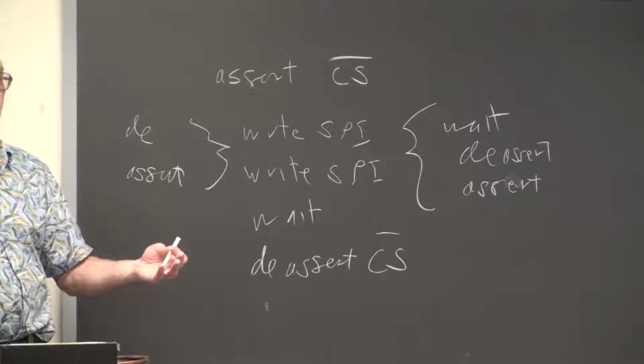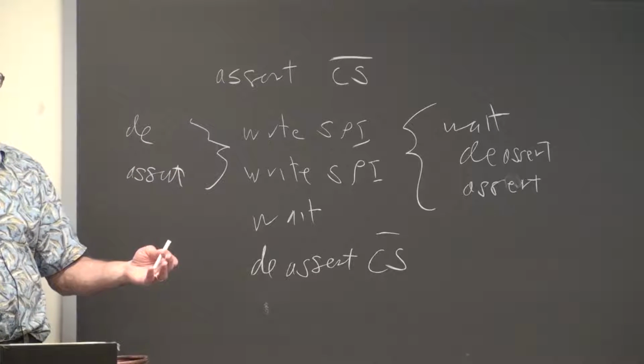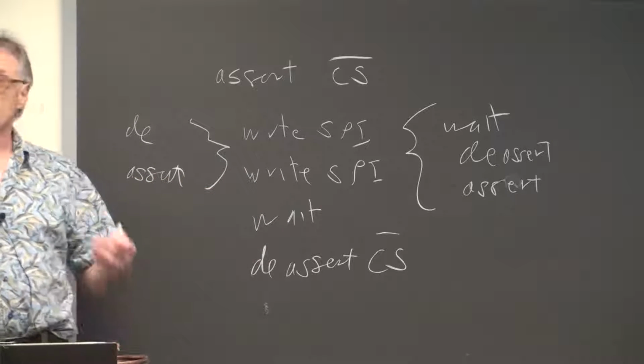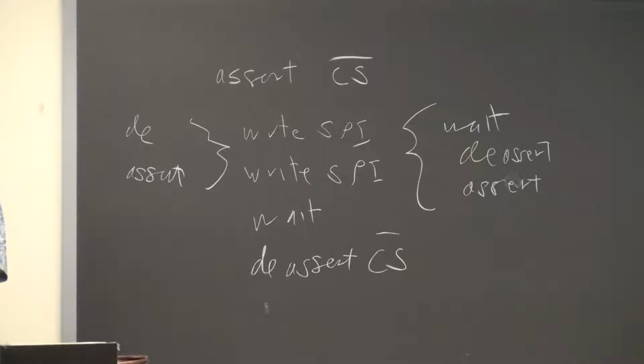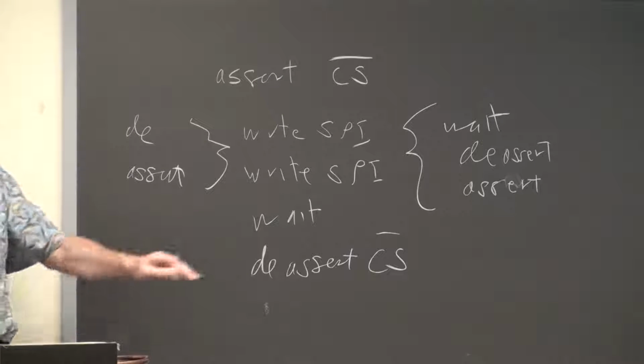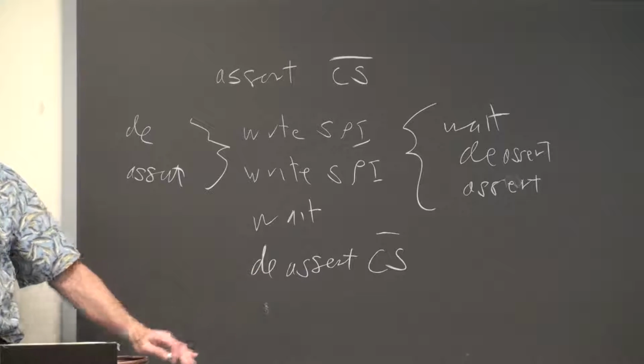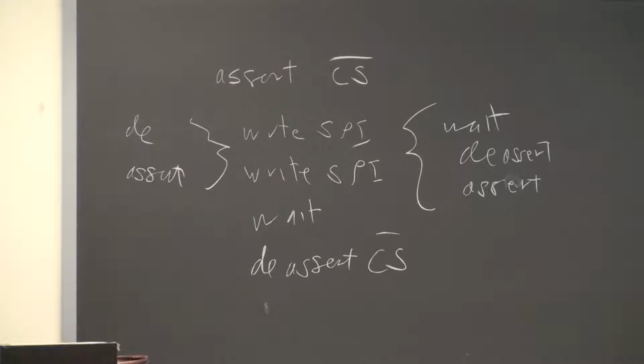There's no deassert. You send the next 16 bits. It writes over the first 16 bits. And then when you deassert here, you see only the second signal and not the first signal. And so the effect will be that one of the channels appears to be dead.